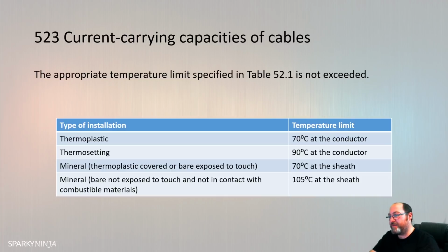So every cable type is here. Copper, aluminium. When you're looking for a cable type, do make sure you understand, first of all, if it's thermoplastic or thermosetting, and also look for if it's armoured or non-armoured, because it's quite an easy thing to miss, and the cables do change.